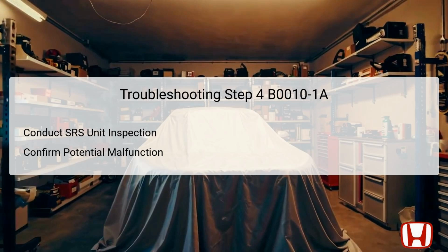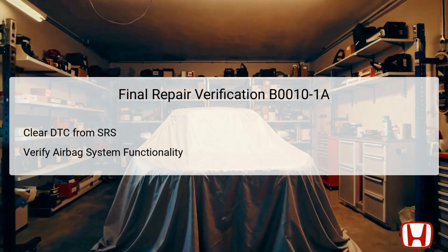Should the SRS unit indicate a problem from the aforementioned conditions, technicians can conclude that it requires repair or replacement. Replacing the SRS unit can restore the safety function of the airbag system, ensuring proper deployment in the event of an accident. After completing all necessary repairs and replacement of defective components, it's essential to clear the DTC from the SRS unit. This procedure allows the unit to reset and establish a baseline for future diagnostics.